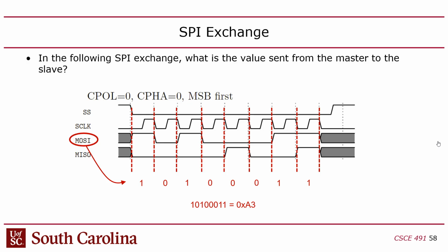Now, you guys might remember, though, that on the RISC-V CPU in 611, there was actually an instruction that did a simultaneous read and write. It was called the CSRRW instruction. Remember that? We actually hacked it to make it not do that, right? Technically, there are some instructions, like, for example, atomic exchange. You might have heard about that in operating systems. In 311, there's an atomic exchange instruction that reads and writes at the same time. But typically, when we do peripheral I/O, it's unidirectional, and we usually call those transactions: a read transaction, a write transaction.